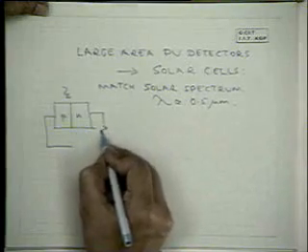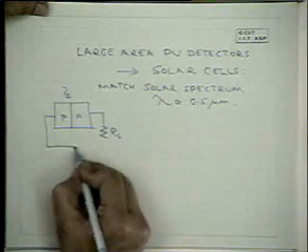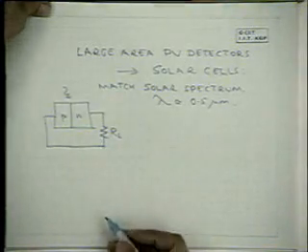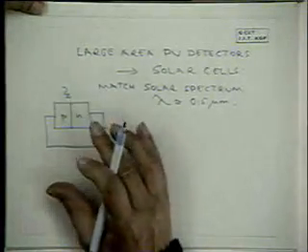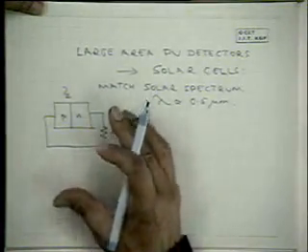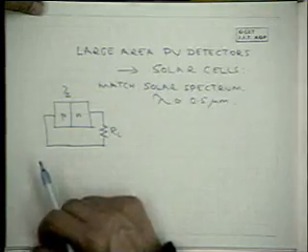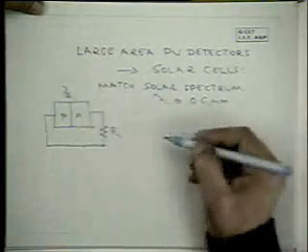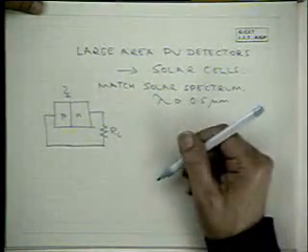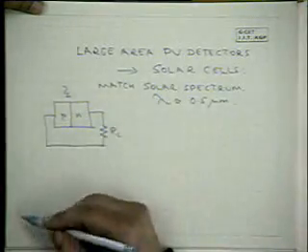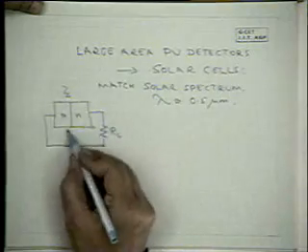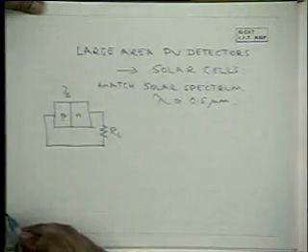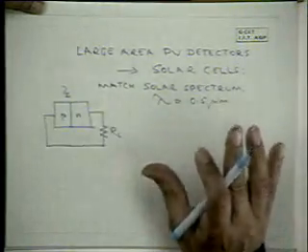So one major difference between photoconductive and photovoltaic devices is that you don't need a bias. You don't need an electric field. For solar cells, obviously, you are generating electric energy from optical energy. So the built-in field is separating the electron-hole pairs.